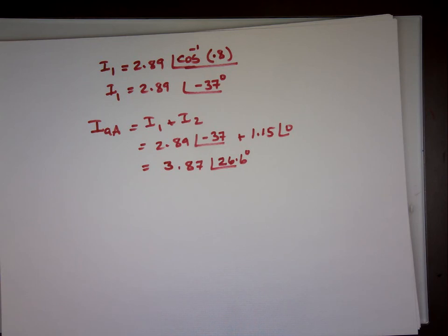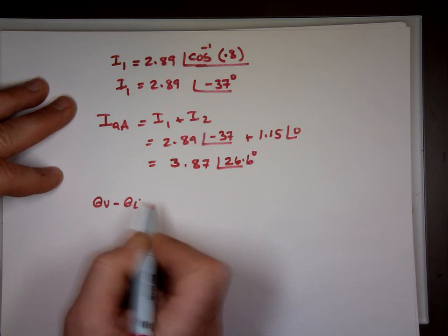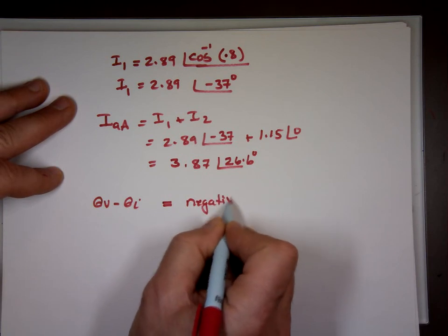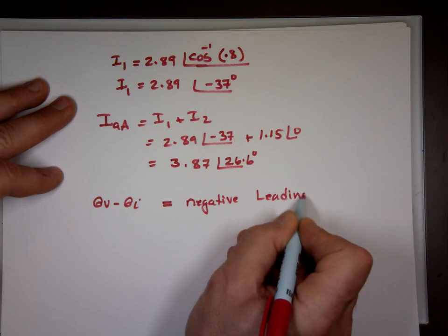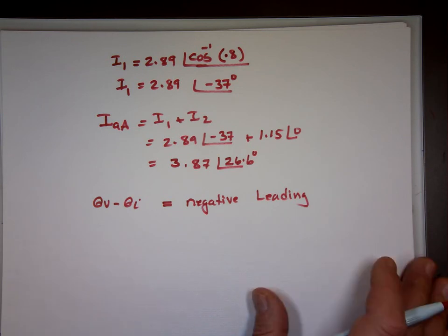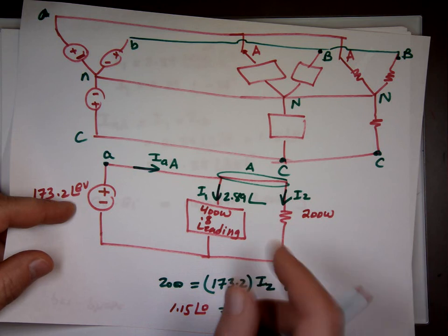So when you get the power factor, it gets the difference between the two angles. Is there a reason why we were able to say that the difference between the two was negative? Well, because it's leading. The word leading says negative, lagging says positive. That means theta V minus theta I. Because it's a leading power factor, this has to be a negative value. Did we just assign that theta V was 0? It could be any number, it doesn't really matter. The difference between them is going to be that number. I'm using that angle also for this, so if it has an angle, that angle is going to show up here. It becomes no factor what that angle is, so to make my math easy, I make it 0.